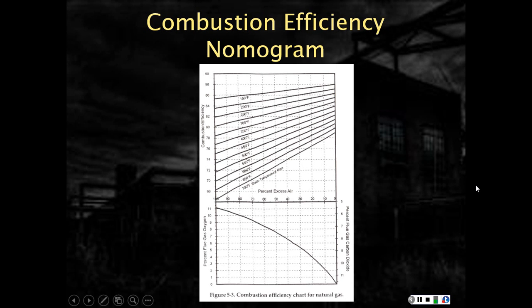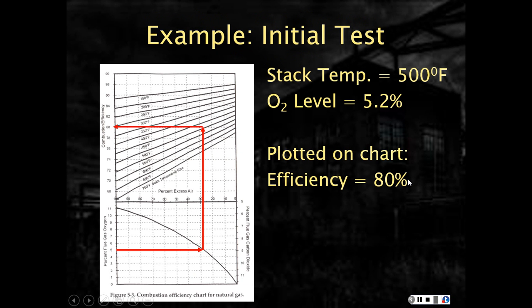Now, most problems assume that I'm going to start making adjustments to my excess air to try to increase efficiency. Now this may or may not impact my exhaust gas temp or stack temp. It'll certainly affect the percent of gases that I'm measuring in the exhaust gas.